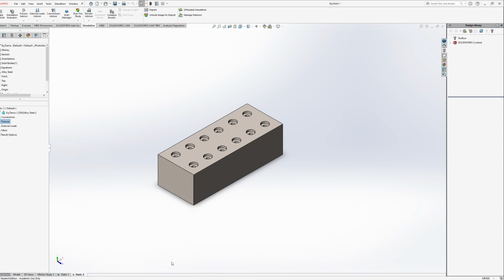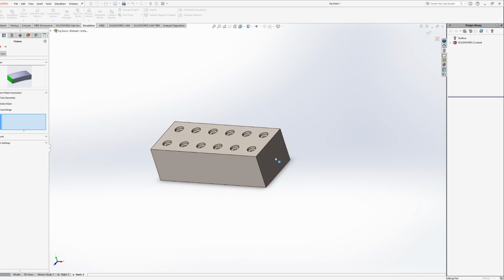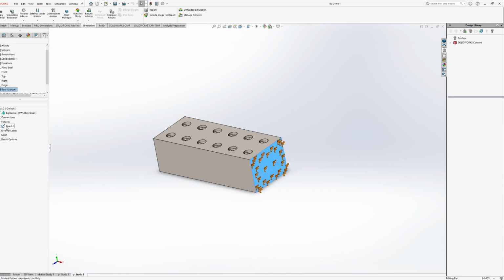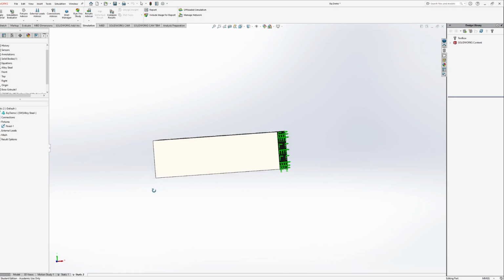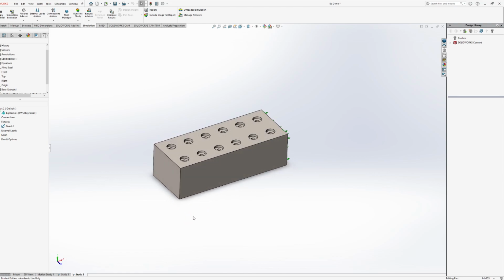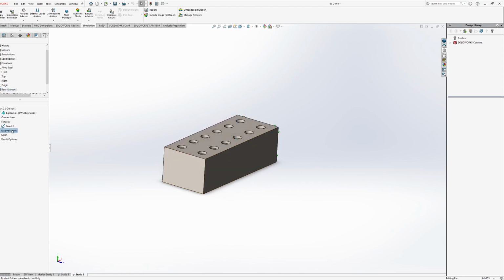But basically what we would really want to do next is ensure that we have that fixture on one side, the right view of our geometry. Now if we mouse over it, we can see that there is a fixed region. You can add multiple fixed regions either at once or separately, kind of similar to adding fillets to something: you can create all the fillets in one, or make several fillets if you want to break it apart a little bit. And then the next thing that we do want to add is a load.